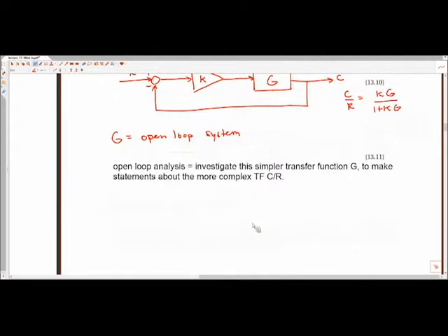And so a transfer function G, we can always say is parameterized by some gain. This is not the gain we're varying, so oftentimes this class would call this K hat. So the system innately will have its own gain associated with it. For the airplane example that we just showed, the gain was 160, and that was just an arbitrary example pulled from a textbook. And it's also going to be composed of a set of poles and zeros. So we can say that G is going to be a function of K hat, its set of zeros,